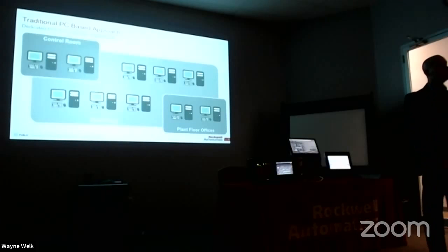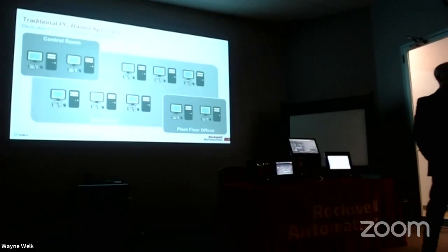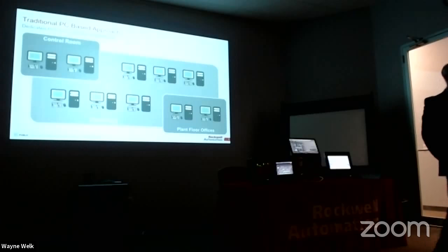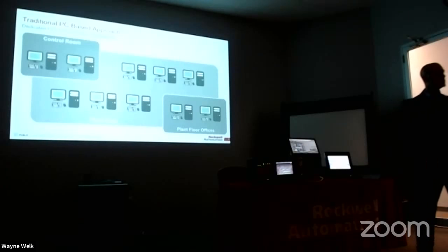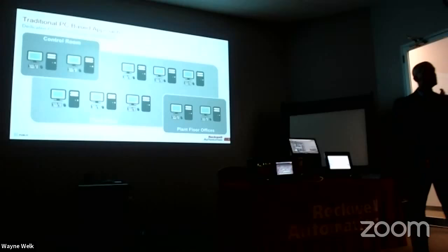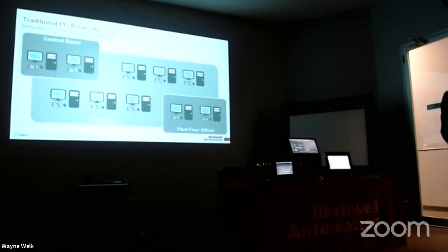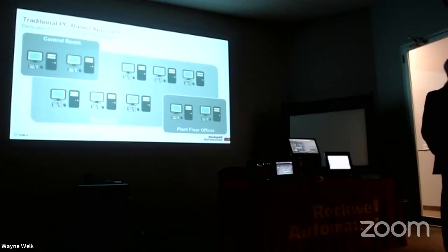What does that mean? It means the BIOS is already in the device. What you have to do is physically go plug a mouse and keyboard in, what have you, get in there, go into the BIOS, and change the IP address to be static. So if you want to manage your IP addresses, you can do that. Another method is, and I'm going to say this from a mixed use environment, if you're not using our product, you're using other products or even using PCs, you want to use your existing equipment to jump into a platform like ThinManager, you can do that.